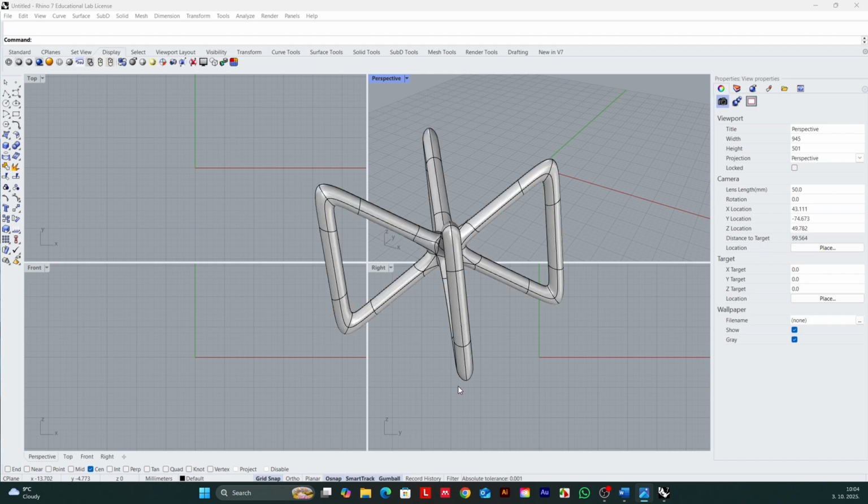structures. A BCCZ, or body-centered cubic with Z struts, unit cell is a modified body-centered cubic or BCC lattice structure that incorporates additional struts along the Z-axis to enhance its strength and stiffness, making it particularly well suited for applications such as additive manufacturing and lightweight design. Unlike a standard BCC cell, which has struts intersecting in one center, the BCCZ adds a central vertical strut.